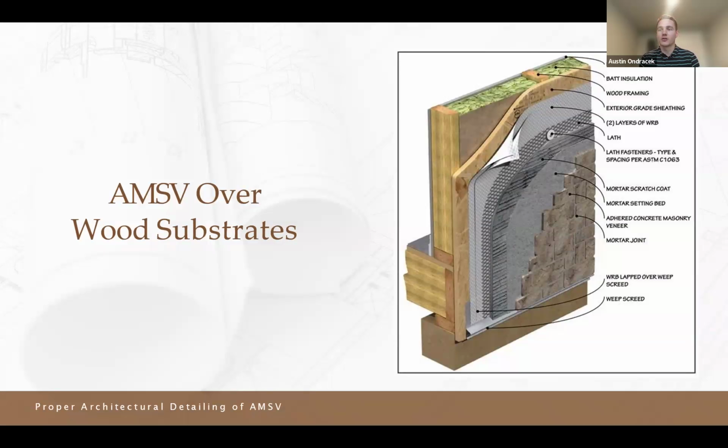Whether it's your water retention barrier, your lath, what type of mortar you use, obviously having a great scratch coat for that mortar to adhere to the stone and be as one unit. Whatever you do that seems like overkill to avoid issues later on, I think you're going to love that you did it on the front end.